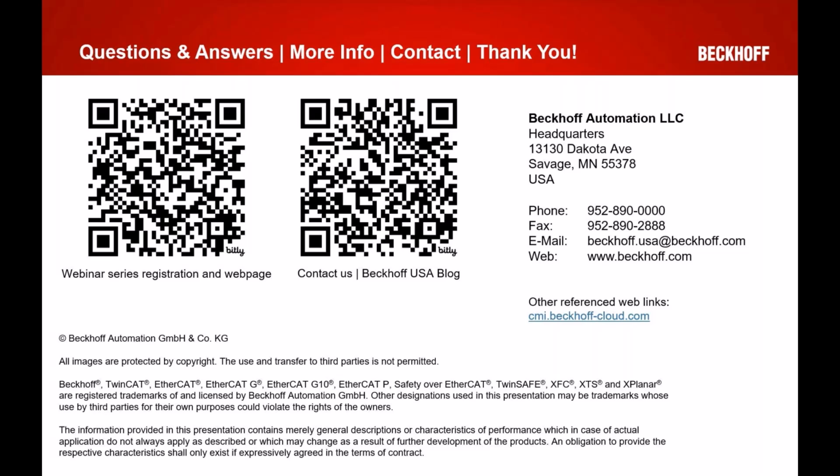If you didn't use that, there is another extension, which we just call the alarm extension, that allows you to specify your own custom alarms. Basically, you point to a PLC tag and set up the conditions that create that alarm. If it's a discrete value, you can just say when this Boolean goes high, throw this alarm. On the front end, it uses all the same controls, the same event grid that we saw in one of the demonstrations earlier. But on the back end, it's using a separate extension because it's not tying into TwinCAT's event system. It's its own alarming system. The extension is called TCHMI alarm, and it allows you to specify custom alarms.